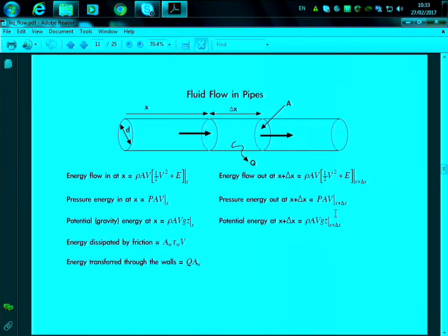So then we input all these factors in the general equation, in minus out equals accumulation. So we have here the inlet, and we have put them all together, the outlet all together, the changes of pressure, the friction losses through the system, and the heat transfer. All these should be equal to 0 in order to obey the conservation law.